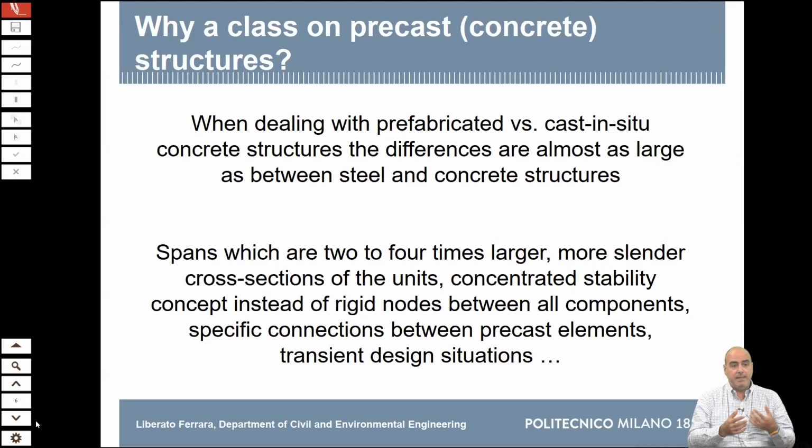Then steel structural elements are made in such a way that the deformability issue, the serviceability limit state issues, or the stability issues govern the design rather than the strength. Whereas in ordinary reinforced concrete structures with ordinary concrete, we first design for strength and then we check the serviceability, which in most cases is guaranteed. Well, in precast structures it is the opposite. Why? Because with precast structures, exploiting better quality control of the material, the possibility to produce with reliability better strength concrete, exploiting pre-stressing, we can go to spans which can be up to 4 times larger than the ones that we use in cast-in-place structures.